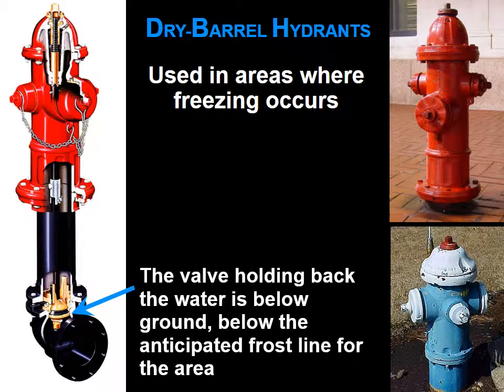If you do not open that hydrant fully, or if you do not close it fully, the pressure that is coming out of your hydrant is also going out those drains, and what will eventually end up happening is it'll blow all the gravel and the dirt away from the base of that hydrant, and either the hydrant's going to come out of the ground or it's going to fall over on you, and the public works guys are not going to be very happy because they'll be out there having to dig it up and replace it.